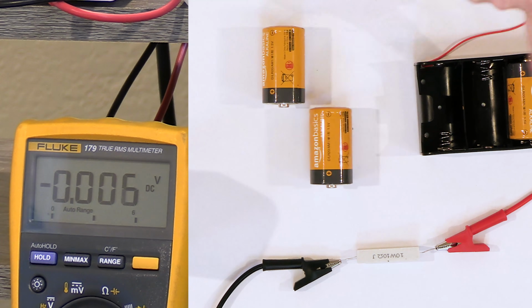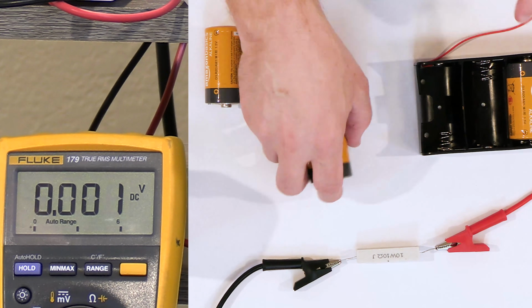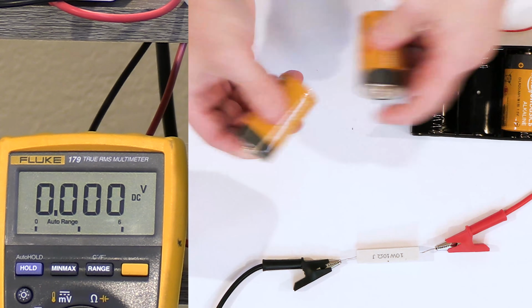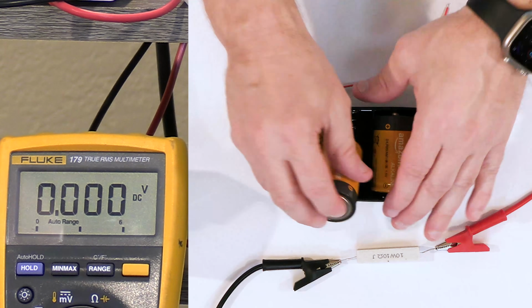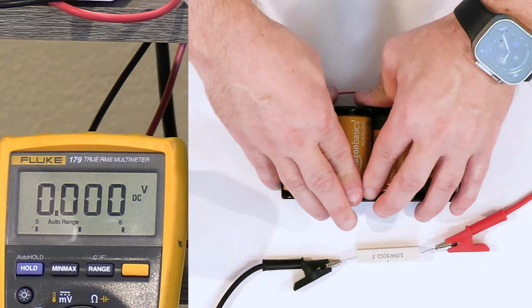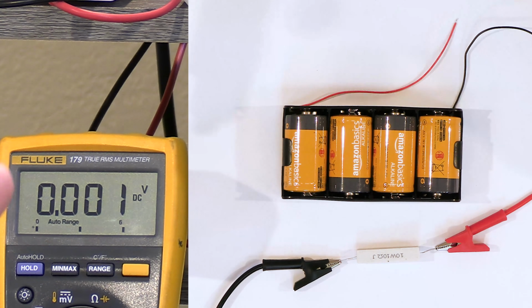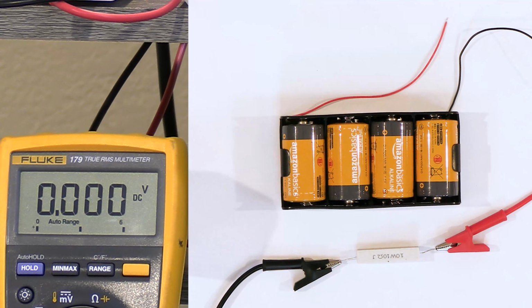So when you see these little devices like this, these little battery holders, all that's going on is it's alternating the direction, but all that's happening is you're putting them end to end to end to end like this. So if I put the flat part on the spring right here, and then the flat part on the spring right here, and these are oriented the same way, all I've done is instead of stretching them out in a line, I've folded them up, but they're still end to end like this. So I know it's about 1.5 times 4, so it should be about 6 volts. Let's see what the actual voltage is.